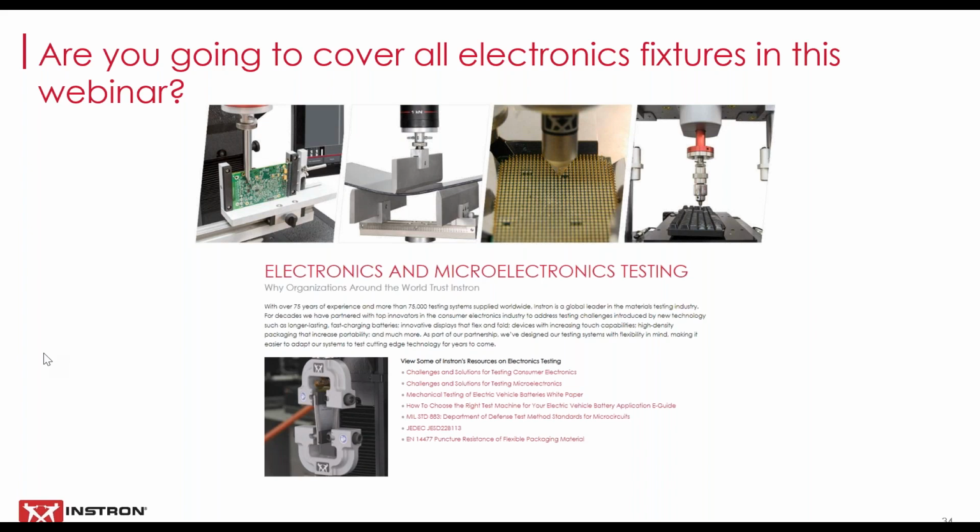So when this button is pressed, there will be a 10 volt output, and you use that to calibrate, and that will just be in your software. And then it works like any other channel, any other transducer that you have on there, where you can plot it and store the data into your data file along with load and displacement. So it's really just a couple of cables, a signal conditioner, and just a couple of minutes to set it up in the software.